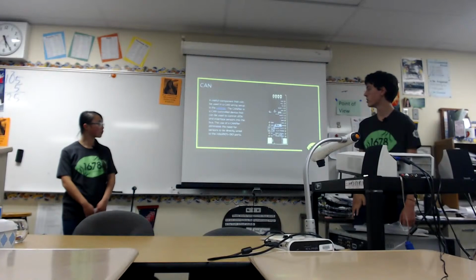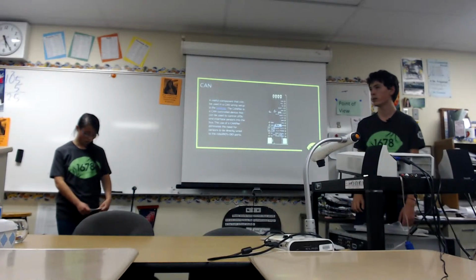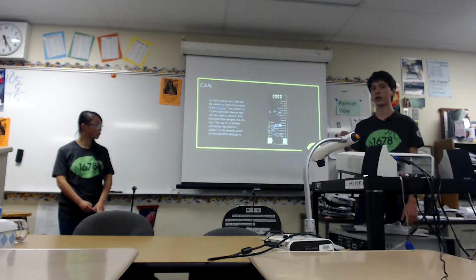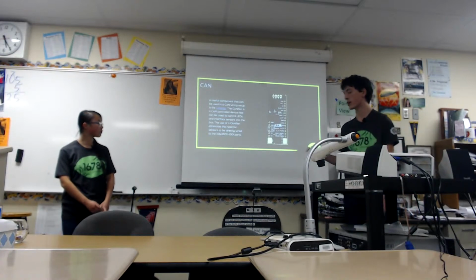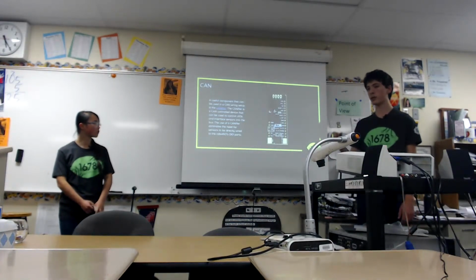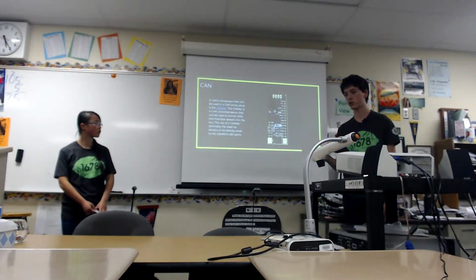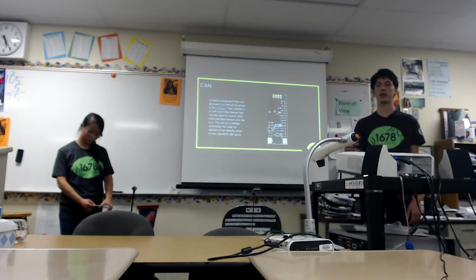Usually when you have a CANifier, what you're going to want to do is have this be at the end of your CAN loop and have a terminating resistor on the CAN port. And then that means with the PDP, you're going to have to change the little connector to the off position for the terminating resistor.